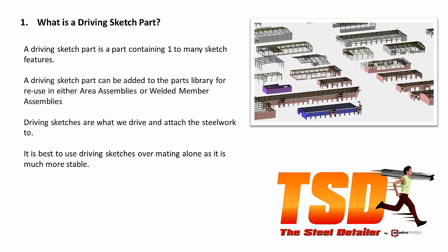Now, the best place to create a driving sketch is in a part. However, driving sketches are used in project levels, area levels, and member level assemblies, and how they are used in those areas or in those assemblies is up to you and how you do it. What we will show you is a way that we do it, and if you follow the way we do it, then when it comes to assessing any issues that you may have, we can pretty much easily answer them for you. So if we're all doing the same thing, we experience the same result.